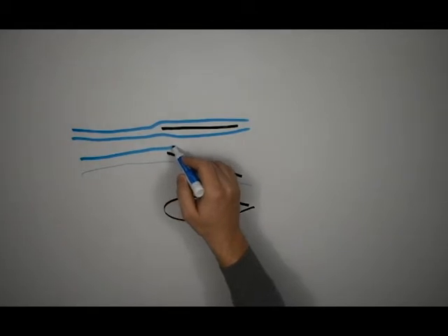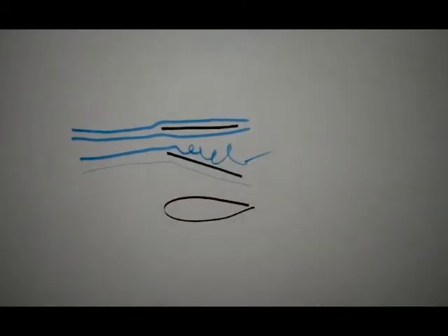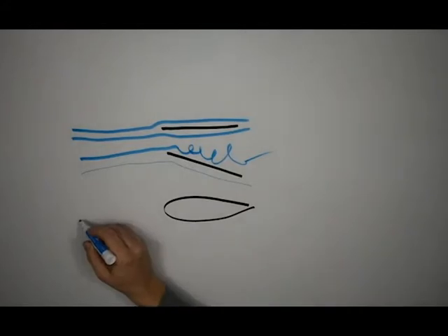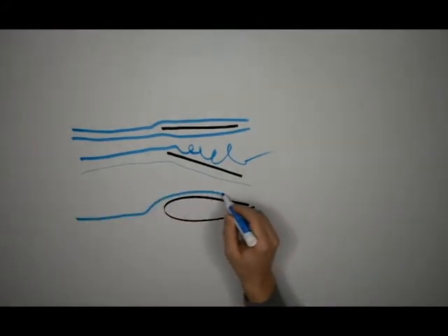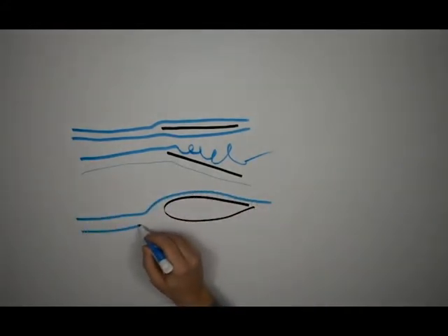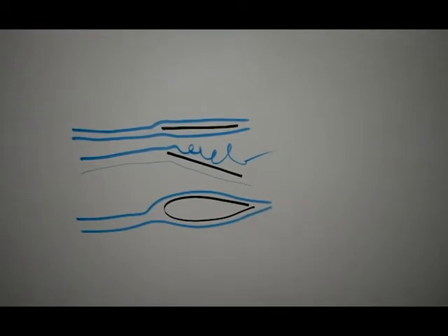But then on the top, you have what's called boundary layer separation, and you end up with the air slowing down a lot. And thanks to the Bernoulli principle, when the air slows down, it also gains higher pressure, so you lose a great amount of control. So when you have a symmetrical airfoil, you don't have this boundary layer separation, and you're allowed to direct the air more efficiently. So when we have zero angle of incidence, we have zero change in direction of our air and zero force in either direction.